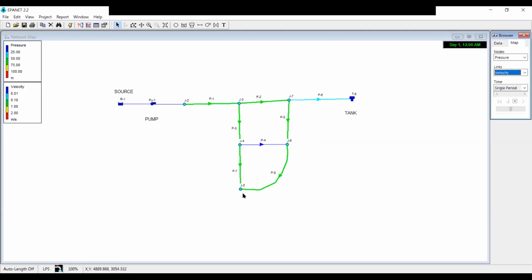This is a safe house in terms of water cut. If you are living here, for example, if there is a break in this pipe, you can take water from this pipe. So the advantage of loop systems is that this house can take water from these 3 pipes. Even if you break this one and this one, it can take water from this one.